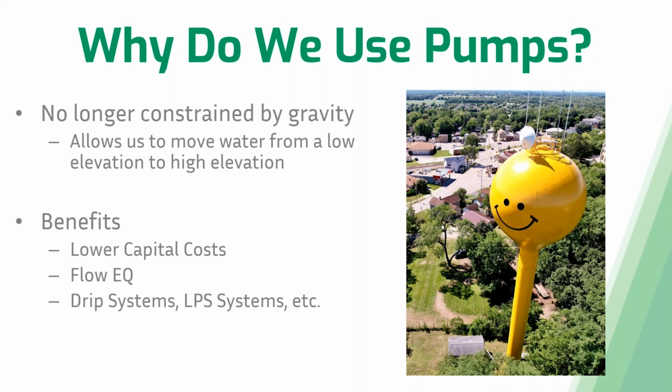Another benefit is flow equalization. What I mean by that is you know how much flow is going to be moving through your system whenever that pump is called to run, as well as the velocities of the water moving through that system. So you know that you're going to keep your solids suspended if you're in a sewage application, and you know how much water is going to be moving through that system, so you can size your treatment facilities specifically around that flow.